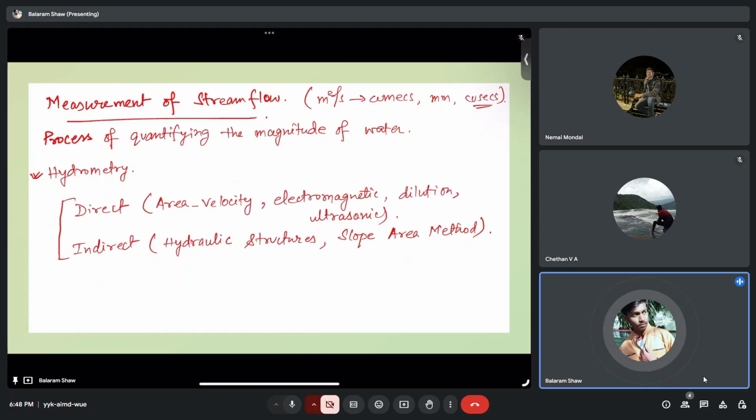Okay. So in this, mostly in some of the processes we'll see that we are finding the discharge directly. But in the direct methods also, in many of the methods you'll see either you are measuring the stage, or the height from some reference point or the water surface, and then by some means we get the discharge. Or in some of the methods we are measuring the velocity, and from velocity you know that we can write discharge as area into velocity, right?